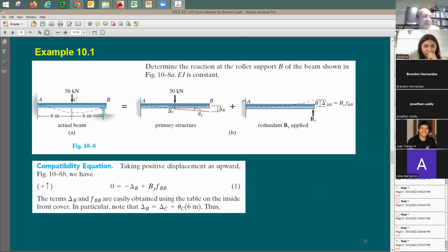And then I'm gonna say I need to have another beam, like the one system, if you like. I'm gonna put here a point load and find out how much deflection is gonna be going upward to resist or to counteract the effect of this having no support at this point. So, okay, how is my equation gonna look?